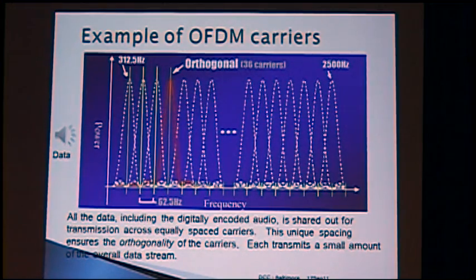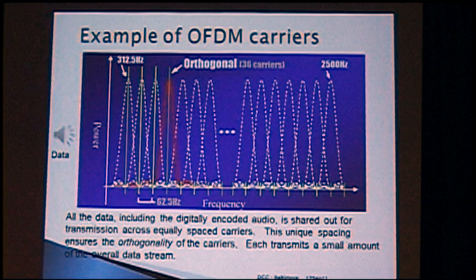Something that they learned from ham radio operators 60, 70 years ago, RTTY. They're running at 50 baud. So again, that's the reason why it's as robust as it is. Now, if you look at something like ADSL, it uses these. There's tens of thousands of carriers on them. DRM uses 460 carriers. So as you reduce the number of carriers, of course, you reduce the RF bandwidth. But at the same time, you have to have a much slower codec because you don't have enough data there.